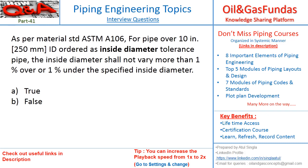As per material ASTM A106, for pipe size over 10 inch, ordered as inside diameter tolerance pipe, the inside diameter shall not vary more than 1% over and 1% under the specified inside diameter. Is it a true statement or false? This is a true statement.